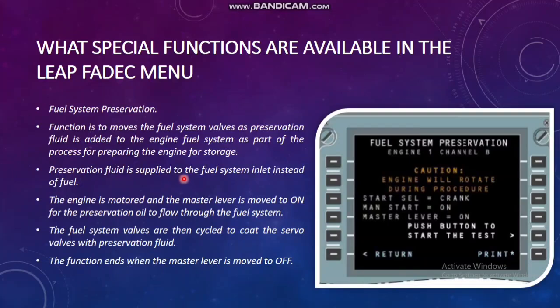Preservation fluid is supplied to the fuel system inlet instead of fuel. So we are using preservation fluid in place of fuel. This will prevent corrosion of the engine during the long storage procedure.